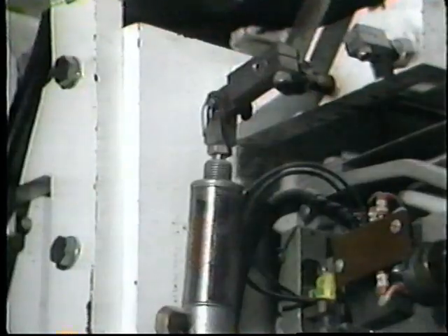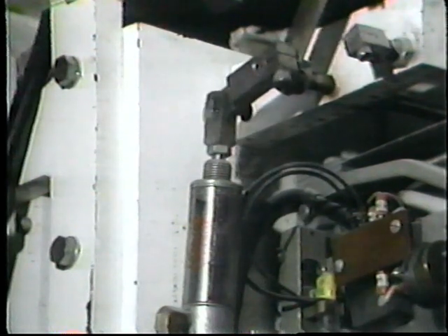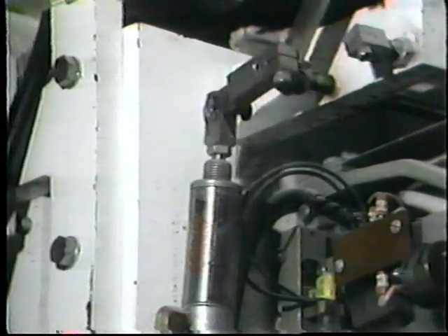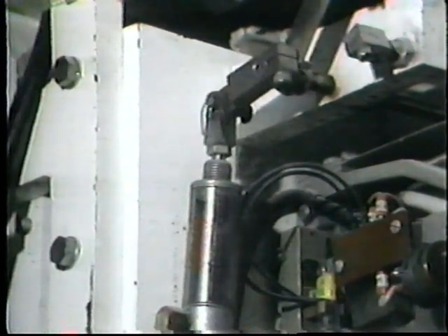But if we want to control the rate at which work is performed, then we must control the speed at which the actuator moves. In a pneumatic system, the speed of the actuator depends upon how quickly the actuator can be filled and exhausted of air. The greater the cubic feet per minute that flows into the inlet and out of the exhaust port, the more rapidly the piston will move. But before we examine flow, we should understand a couple of important facts about pneumatic circuit operation.